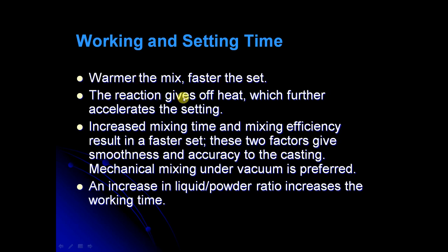Coming on to the working and setting time: the warmer the mix, the faster the set. The reaction gives off heat which further accelerates the setting. Increased mixing time and mixing efficiency result in a faster set. These two factors give the smoothness and accuracy to the casting. Mechanical mixing under vacuum is preferred. An increase in the liquid powder ratio increases the working time.